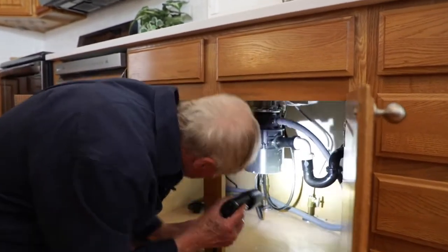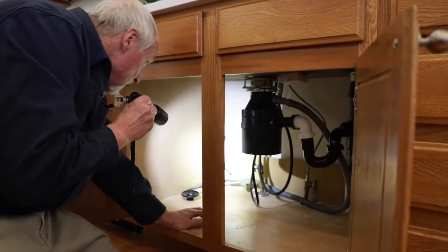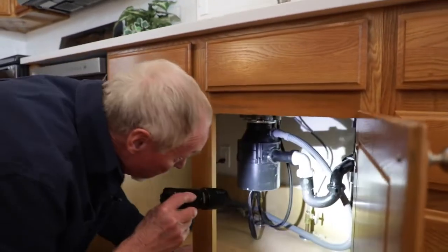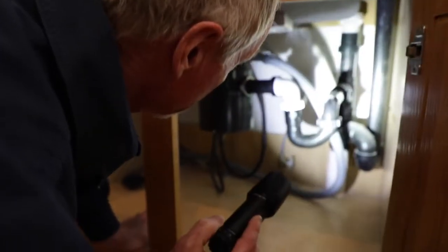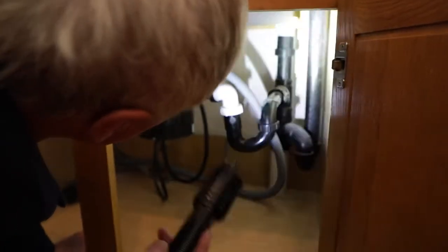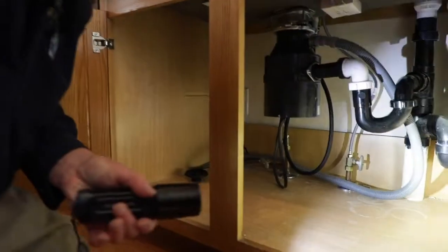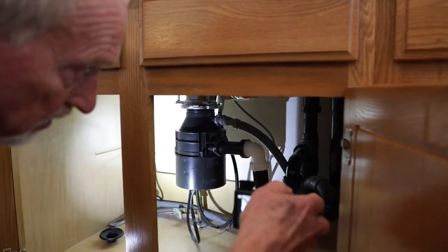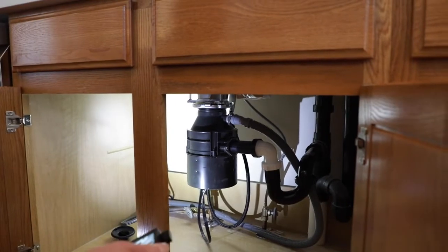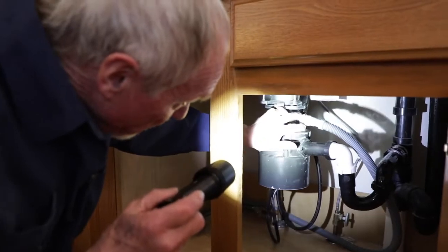Also under here, looking to see our wiring to our disposal looks fine, and our plumbing looks okay. So they have a separate drain here for the dishwasher that they didn't use. Shame on them for that. In this case, that would solve our high loop problem if they had, and quite frankly, I'm going to take a photograph of that, and I'm going to have to write a little essay in my report explaining that they did not plumb this correctly, because you should not use the knockout.